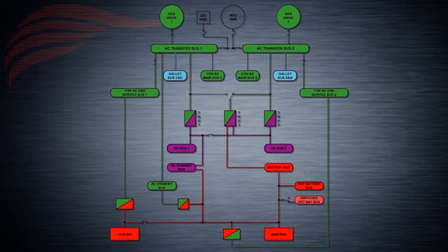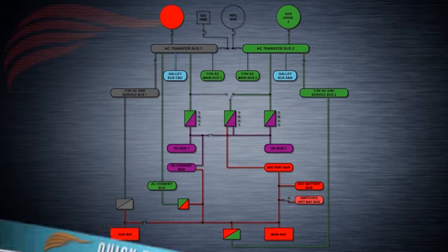AC power in the 737NG is generated and supplied from 4 independent sources: left engine-driven generator, right engine-driven generator, APU starter generator, and external power. The AC system is designed to prevent any two sources from powering a same transfer bus at the same time. If any AC power source is being overloaded, the system automatically removes electrical load from it and channels it to another AC source. This feature is known as load shed.